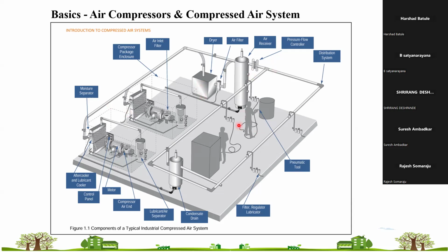We have put the actual operations in idle. You need to start your stopwatch when a load cycle starts. Let's say at 6 bar the load cycle starts. You need to start your timer, and at whatever time 7 bar is achieved, the compressor will go into unload cycle. So you need to measure the time for load and the time for unload. At 7 bar it will start to unload, at 6 bar it starts to load.